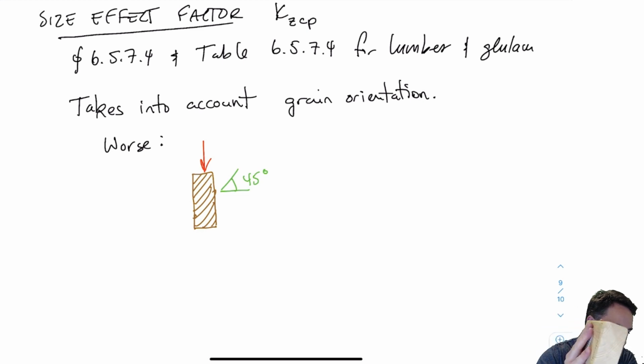If I flip it the other way, maybe I'm not close to 45 degrees anymore because the grains have turned to become more vertical. Now, if I lay the piece on its side, then actually part of the bearing surface is likely not to be at 45 degrees. So you see here about half of the bearing surface is at a 45-degree angle. But by the time we get over to this side, it has rotated around so that part of my bearing surface is now at a flat angle, right? Which was not the case here.